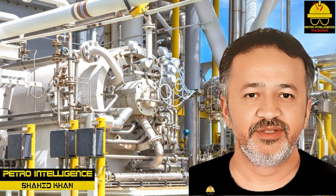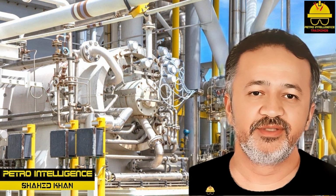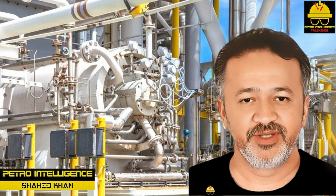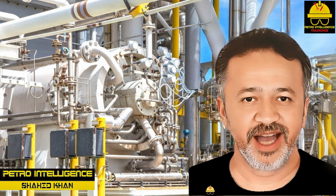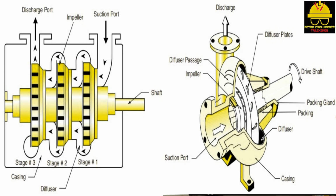Centrifugal compressors. During operation, gas enters a centrifugal compressor at the suction inlet and is accelerated radially by moving impellers, as shown in the picture. Centrifugal compressors have one moving element, the driveshaft and impeller. In a centrifugal compressor, the impeller discharges into a circular, narrow chamber called the diffuser. This narrow opening completely surrounds the impellers.